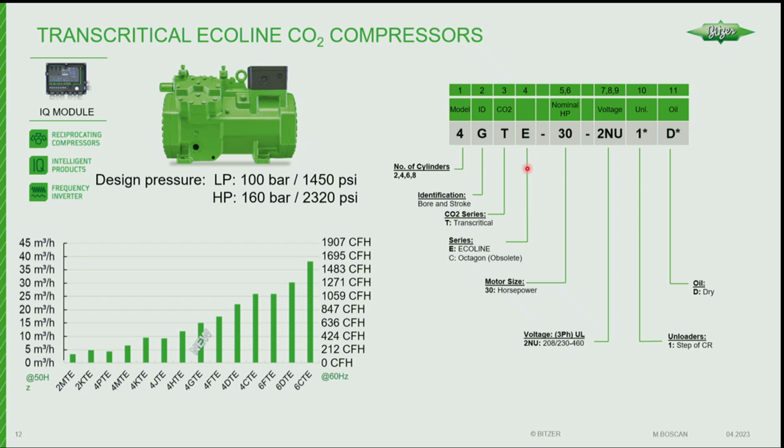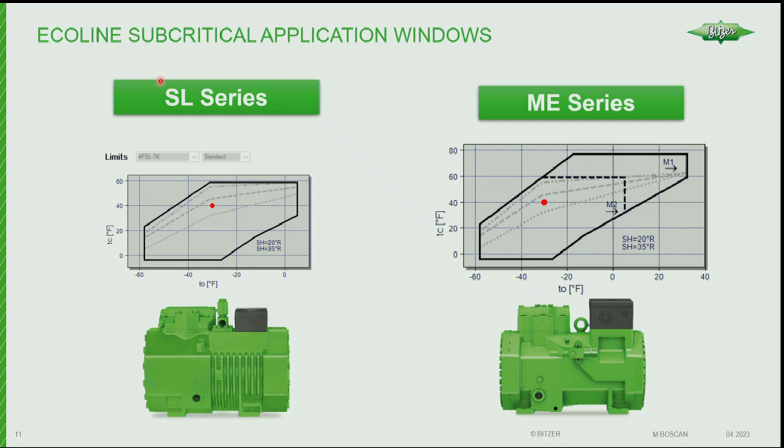This has a pressure relief valve as well, but this pressure relief valve is on the discharge side. So it's over here. It's connected to the body of the compressor, not the service valve. That's another difference. The SL series has the relief valve up here on the service valve. So when you close that service valve, the relief valve is in play.